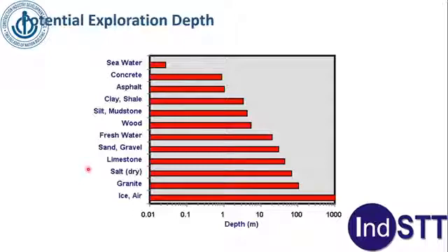For underground utilities, 5 to 6 meters is what we look for, and that is what the appropriate frequency of GPR will provide. So penetration depth and the ability to locate targets at any depth is strongly dependent upon local soil properties. Depth of penetration is also limited by the presence of highly conductive material. Highly conductive soils, as I said, can render this method completely ineffective.